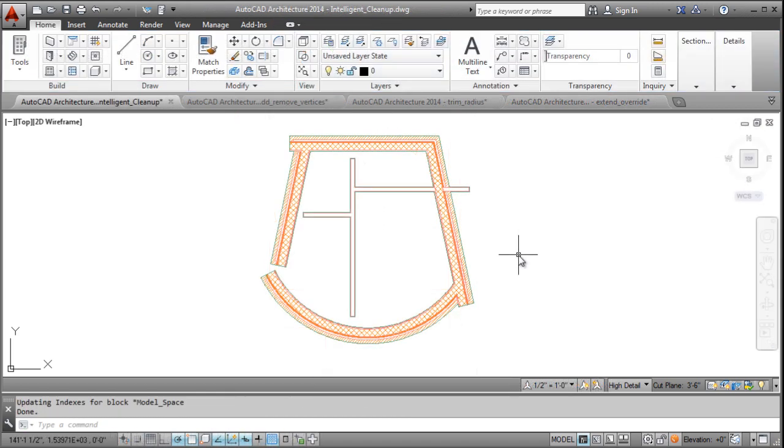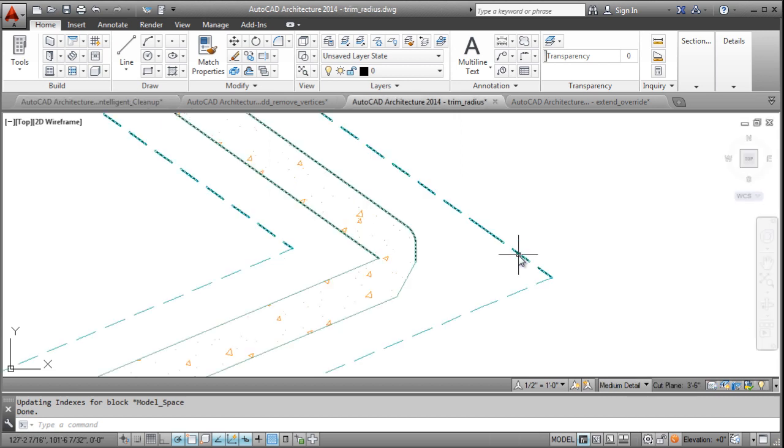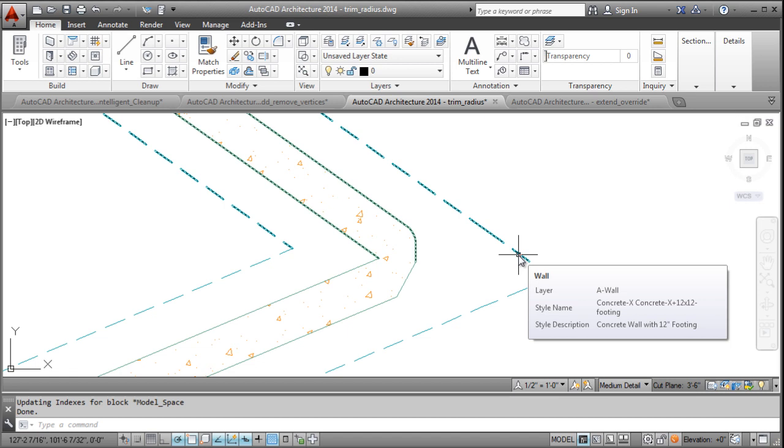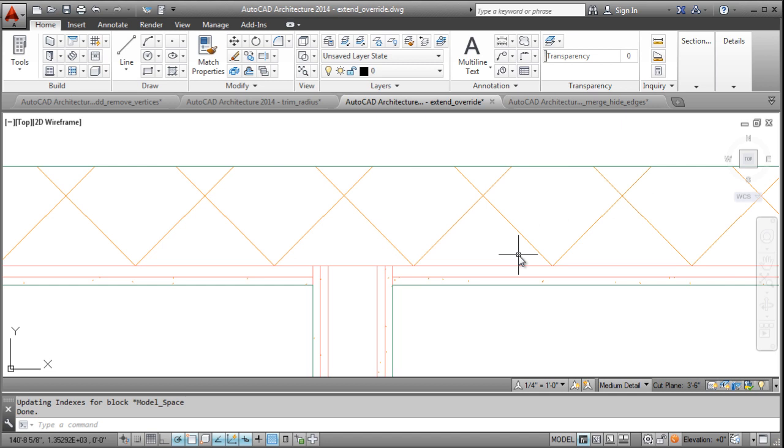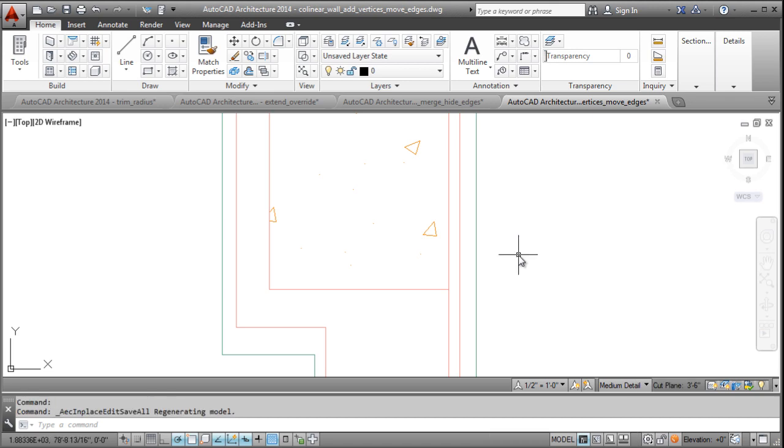With the Wall Edit in Place command, you create custom wall junction cleanups according to real-world needs. In this way, you avoid extraneous detailing. What you see in the plan is what you want in real life. The skills you require are some very familiar AutoCAD skills. You are building on your existing skill set, and because you draft the wall cleanups, you are not limited to a small selection of product-derived solutions. You provide the customized solution.